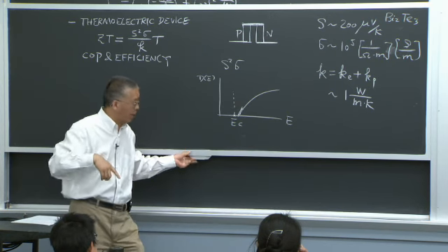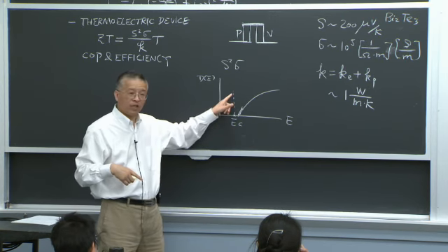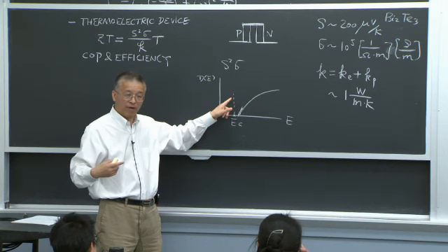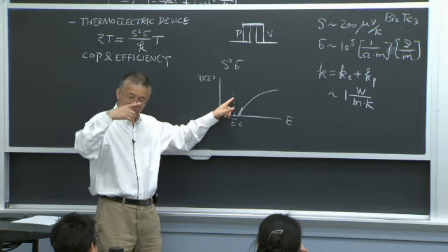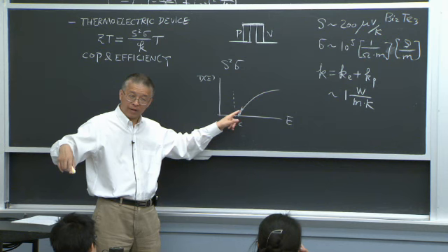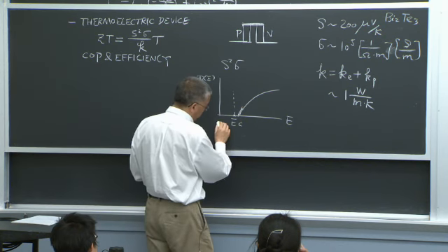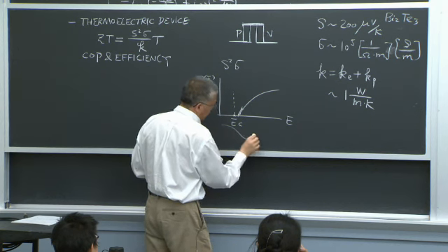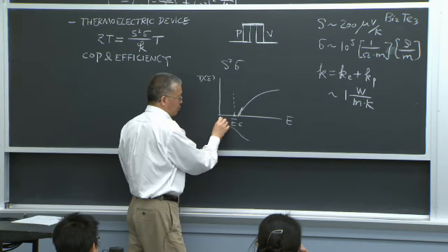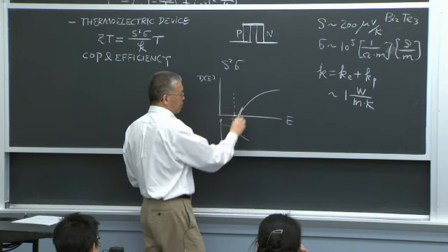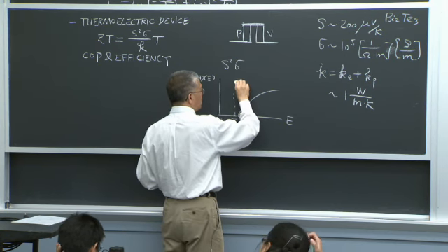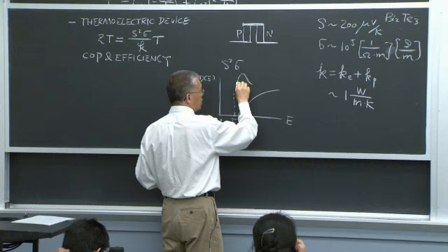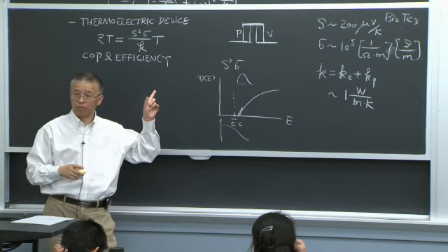Because of the Fermi-Dirac. The Fermi-Dirac at EF is a 0.5 distribution. And the exponential decays very rapidly. So there are not many, so if you plot per energy level, what's the occupancy? This is the Fermi-Dirac distribution. And this times this means this is EC, only a small portion. These are the portion that contribute to charge transfer.